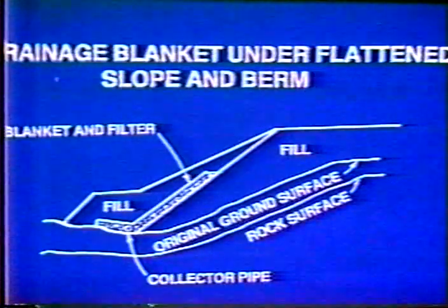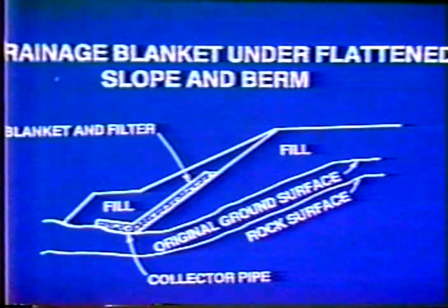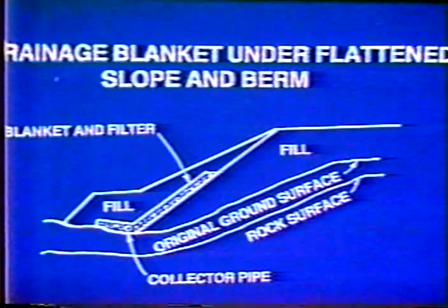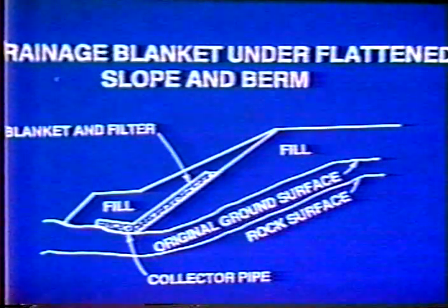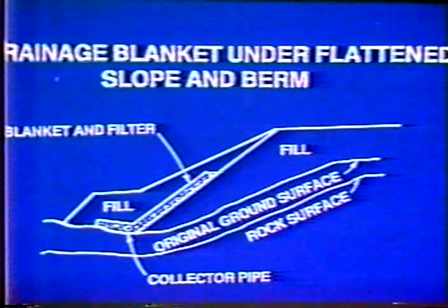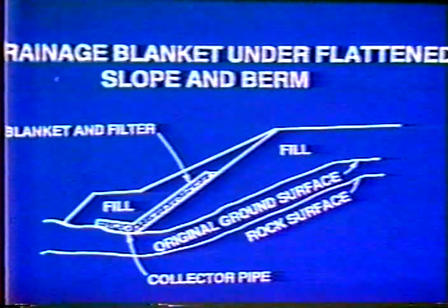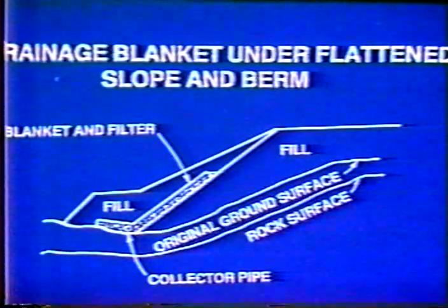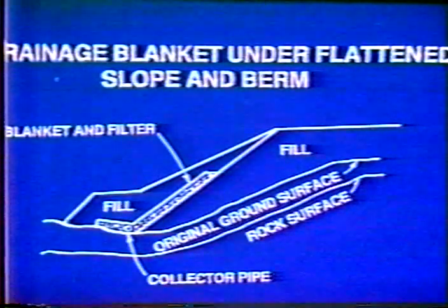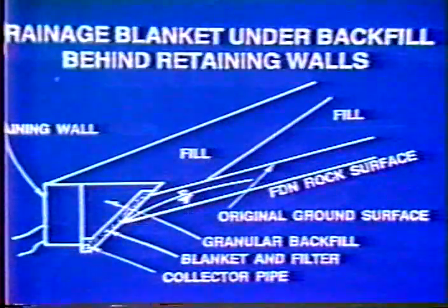What we're basically trying to do is put a draining material back in against the excavated slope. We're trying to control the groundwater. In other words, we want to keep that groundwater out of the new fill, because if the water gets into the new fill, then it's going to lower the strength and lower stability.